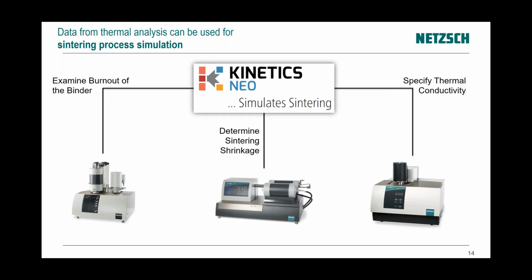In the middle of this picture, you see our dilatometers. Those instruments give you information about the sintering shrinkage in the sintering process step. And on the right-hand side, you see our light or laser flash equipment, which gives you information about the thermal conductivity during the process. All the data of these instruments are used as input in our Kinetics NEO software solution, which is able to simulate sintering and debinding processes.